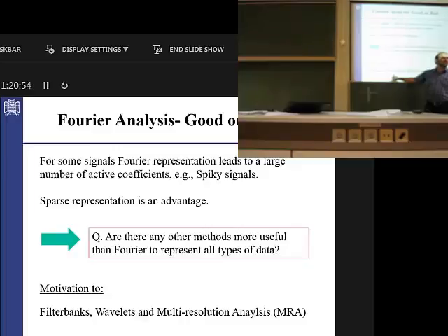In many cases, like denoising in image processing or speech processing, you don't care about the frequency, you just care about the details of information, which is not important and just belongs to the noise. You can ignore that using the wavelet transform. So in those cases, wavelet makes sense.